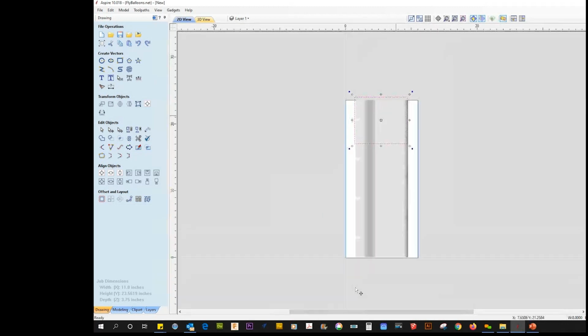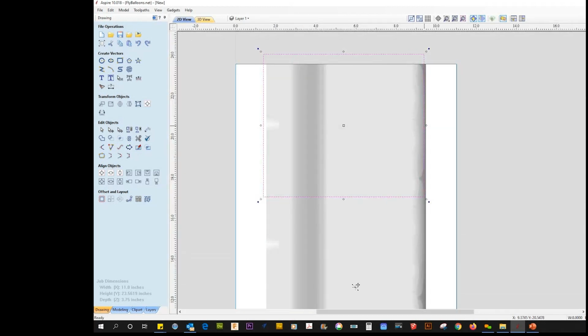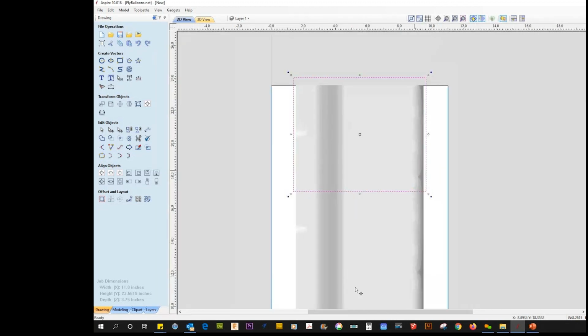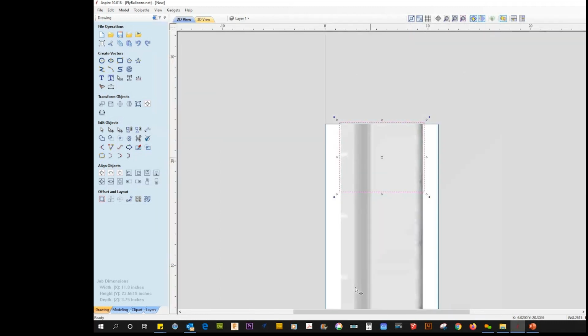And what you have done, you have changed the tool strategy from just normal carving on a rotary to an indexing, because now you're going to force the tool strategy to stay in this area by selecting that. So I copy and I paste and I bring that down.